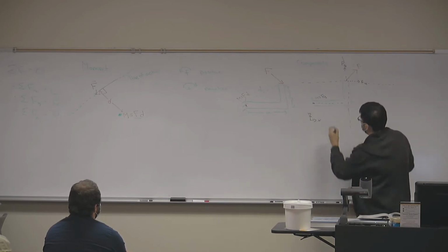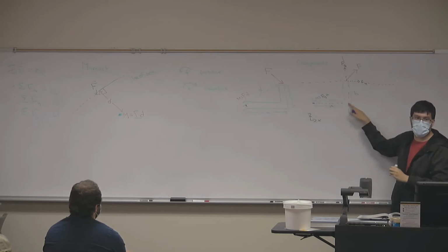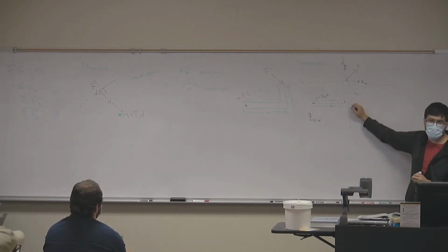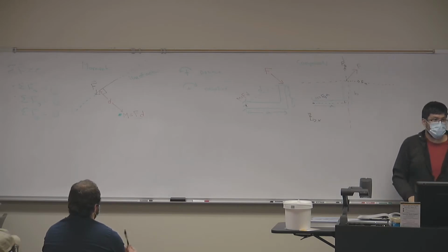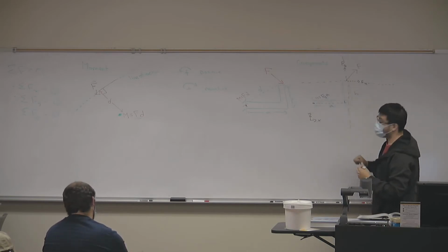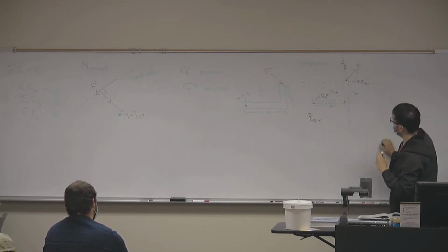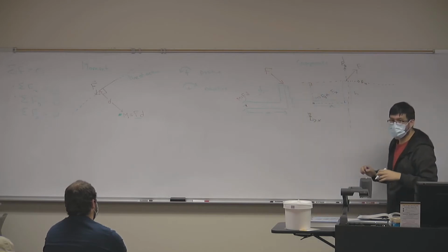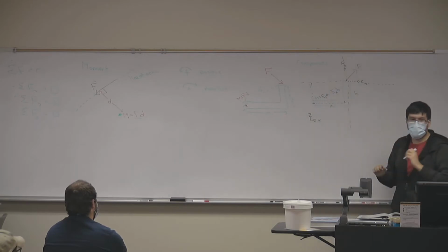So I call them A and B. I'm going to use the same terms again. So Fy times A. Now why A? Because A is the distance that gives me a 90-degree angle between my point and the line of action of the force. Does that make sense so far? Okay. Likewise, if I want to find the moment from my x component of the force, I get my force along the x direction times the distance that gives me a 90-degree angle with the line of action of that force. And that distance, I mentioned, is b.